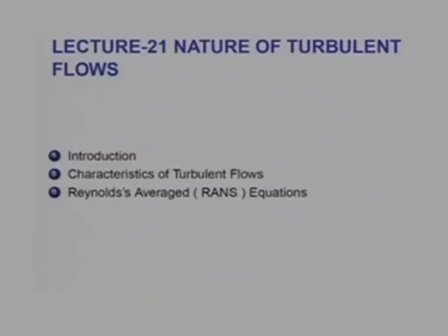And therefore, we would look at some important characteristics of turbulent flows and then understand why statistical averaging is absolutely essential to be able to track theoretically the turbulent flow, which in turn would give us the ability to predict the friction factor and the Nusselt number, just as we managed to do in laminar flows.